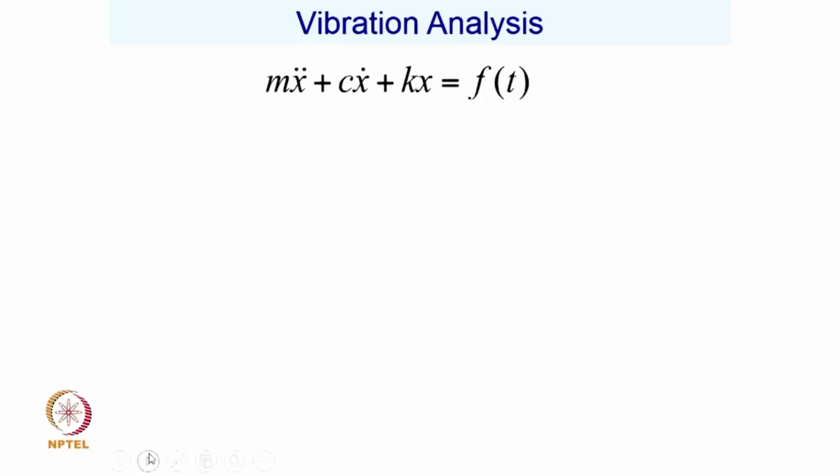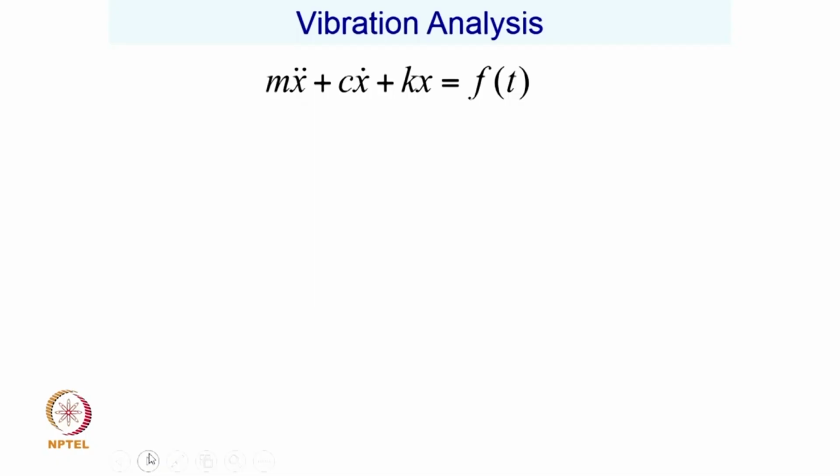And typically in the process of converting a mechanical system into its vibratory model, we are all the time looking at which constitutes the inertia, which constitutes a dissipation element, and its associated parameter value, and what is the stiffness element in that. And most of the times, as we discussed, these coefficients, mass, stiffness, and damping, are constant, and it has more important mathematical implication that the solution of such governing equation that we derive is simpler to obtain whenever these coefficients are constant, and that is the reason why we always, given a choice and given the context, treat these coefficients constant and get first cut solution, and that is what we always intend to.